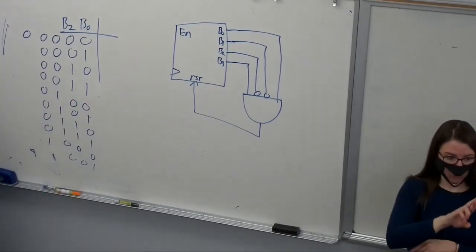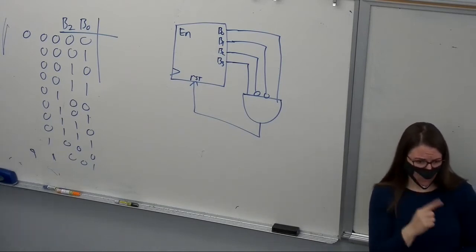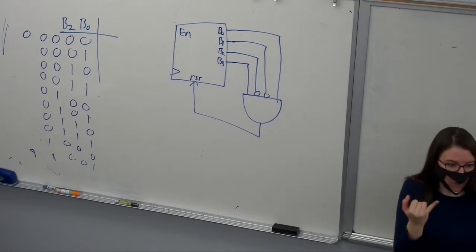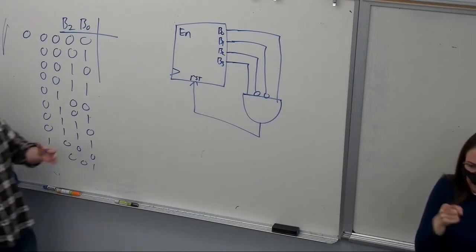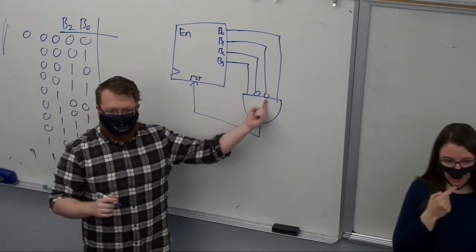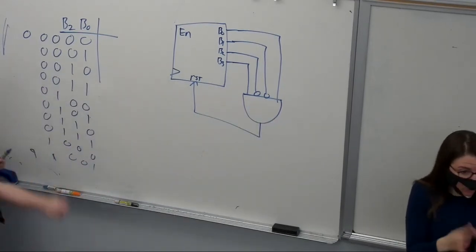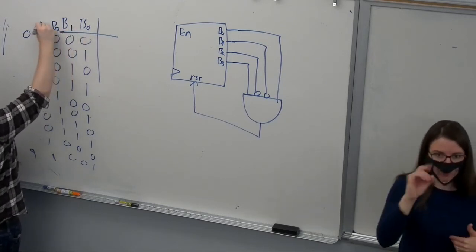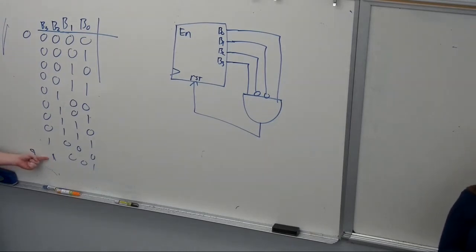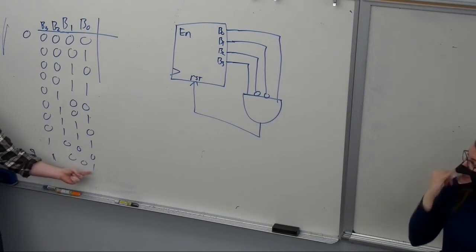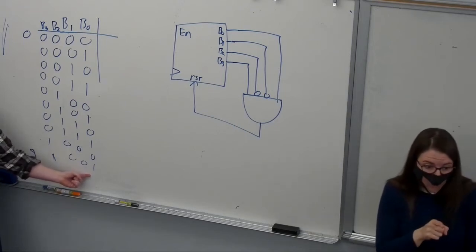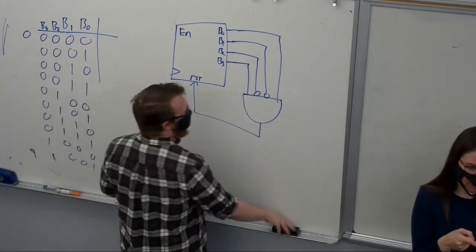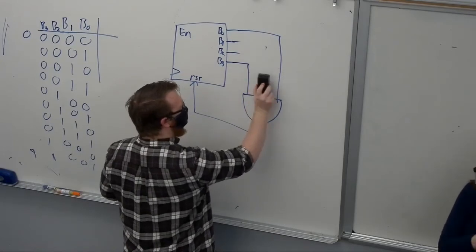Honestly, you wouldn't even need the 4-way AND gate for this one, because that's the second term where bit 3 is there, and you don't care if it triggers on ones after that because it should trigger before those. Exactly. What he was saying is these two are irrelevant. I'll write these out: B0, B1, 2, and 3. The first time that bit 3 is true and bit 0 is true is when I reset. So anything after that is don't care. It doesn't matter because I should never get there. So these two middle ones can just go away.